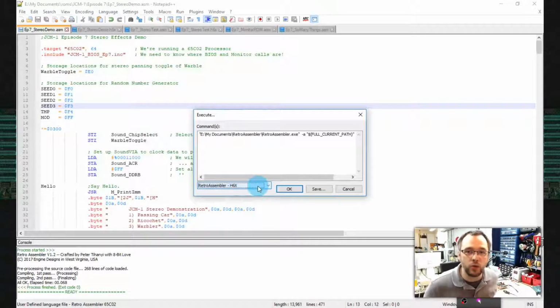Now, the HEX format is a very simple text-based format that has each line with its beginning address of the data on that line, and then the bytes in sequence. It almost looks exactly like an Apple II program listing, a binary program listing. It's crazy. But it doesn't quite match the format my computer is expecting to receive if you were typing a command into the command line. So I have to do some modifications to that.